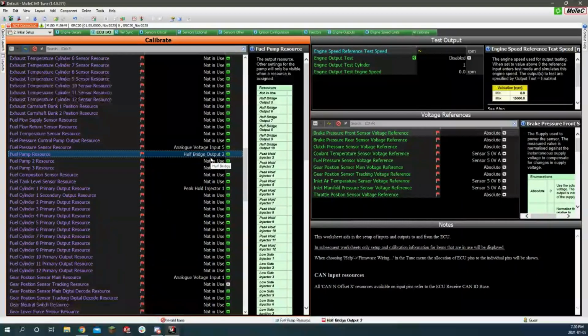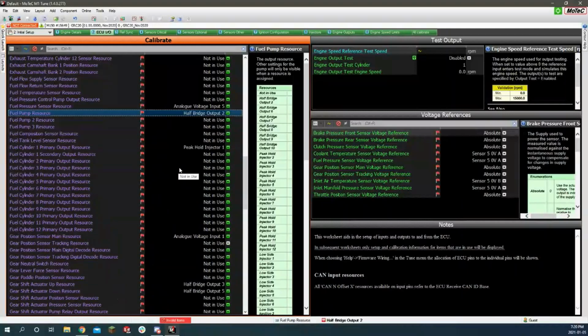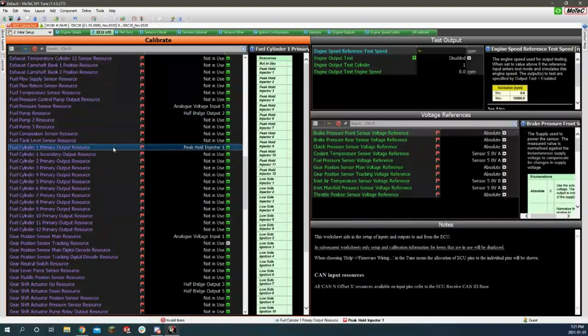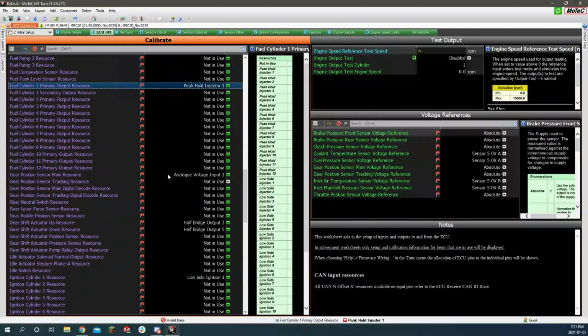Was this going to be a relay, right, Marco, for the fuel pump? Yeah, I think that's what we were currently planning on, running a fuel relay. But again, that's something that we can change in the future. It'd be really nice to be able to step down the fuel pump and run it at a lower power when we don't need all the fuel. Just saves on electrical power, which we really need because we don't have a huge stator to generate electricity. That's just the injector, the fuel injector. There's only one of them.